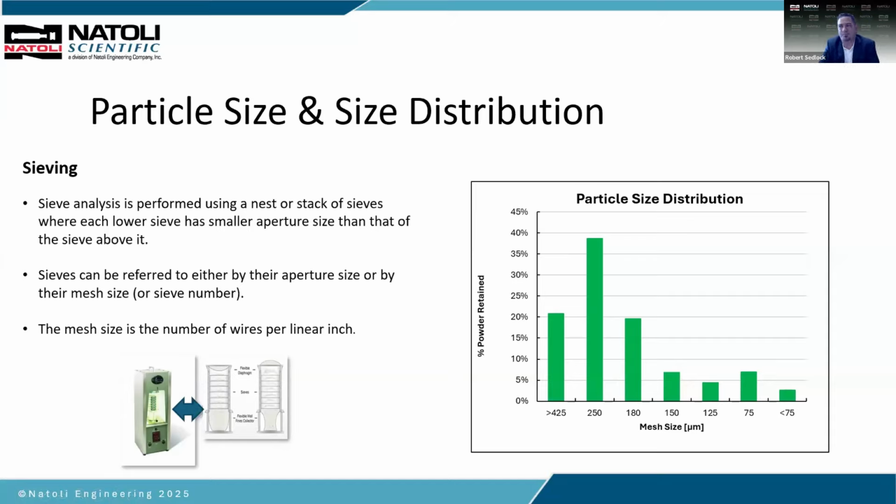Okay, so density is very important to us, understanding the bulk, the tap, and the true. I'm not going to read all this, but this is how you can determine your bulk density. You have a graduated cylinder, and you carefully pour the material in. Let's say you have 100 grams of your formula. Pour it in, get the volume. Mass over volume gives you your bulk density. Again, we're looking for above 0.2, above 0.25 grams per mL.